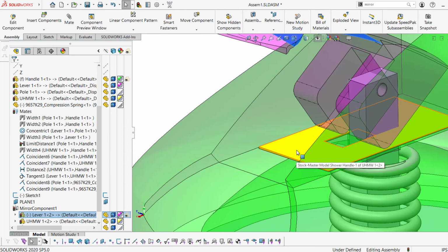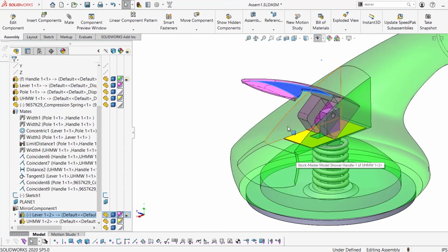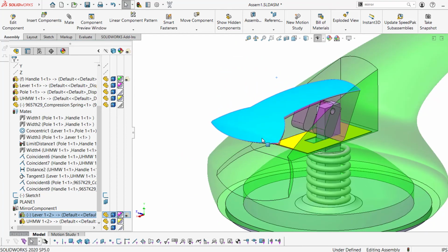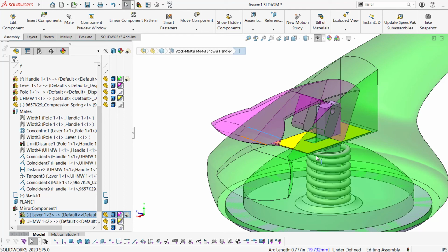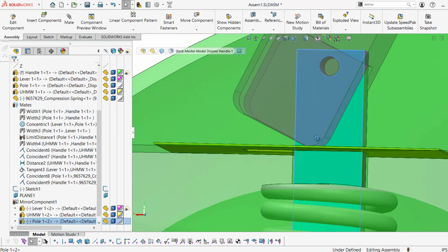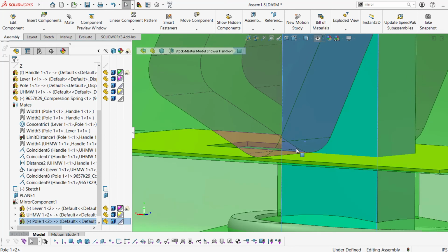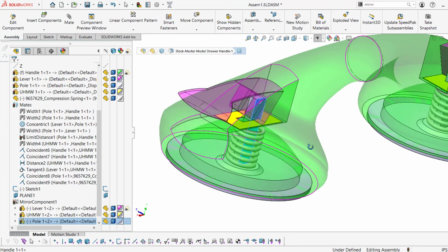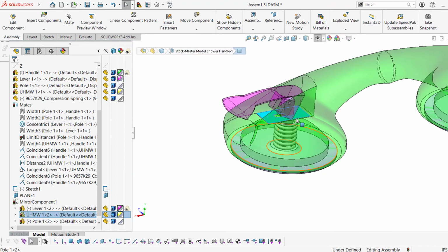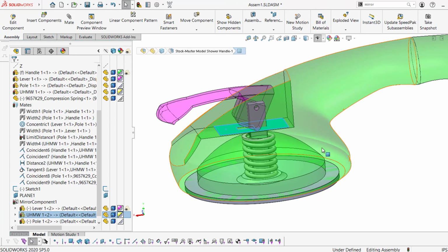I didn't really test the material properties, but it makes a lot of sense to put UHMW where the yellow part is. As you may notice, this part right here, this curvature of the pink handle is going to come in constant contact repeatedly on this surface. And that's why it's a perfect place for UHMW.